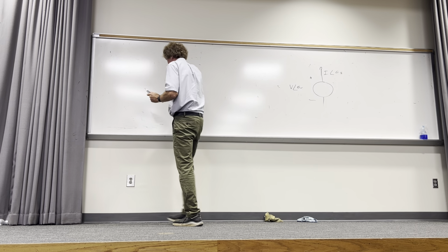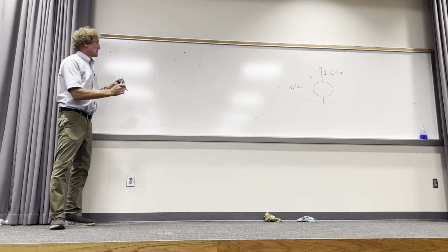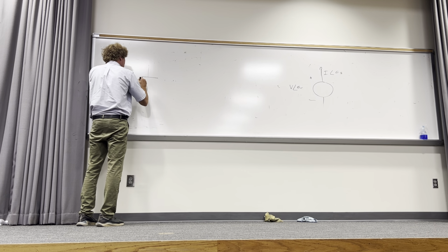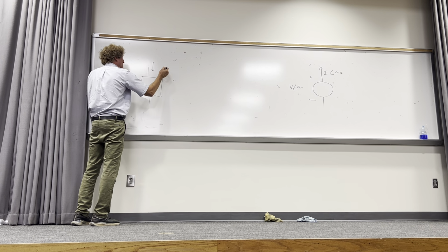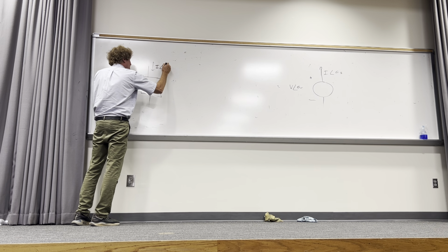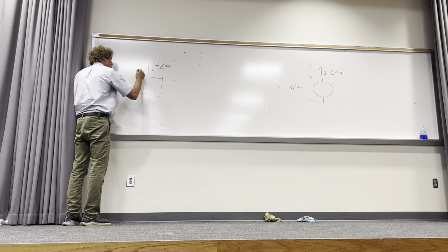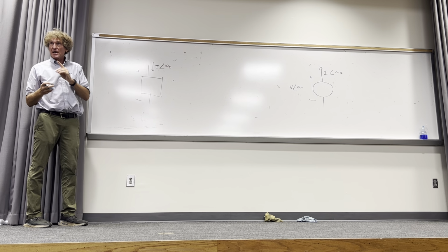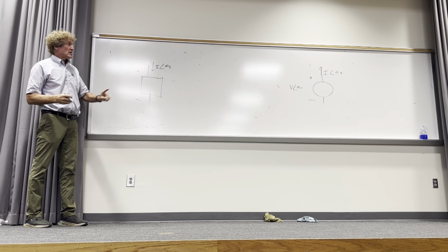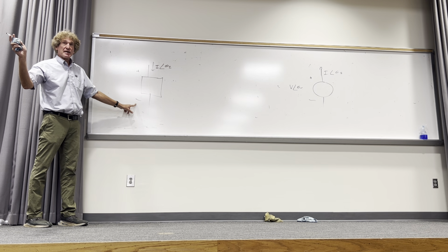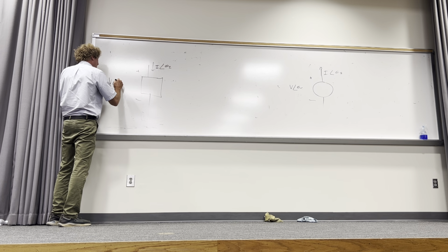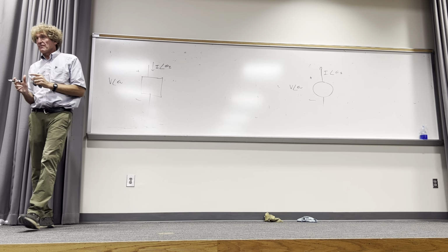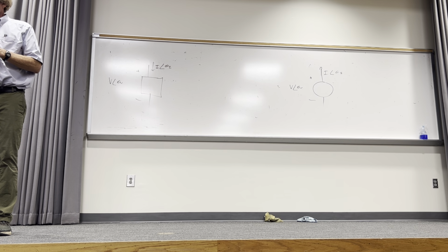And what I'm about to show you is true generally. If you have something, it really doesn't matter what it is, and this something has a current going into it, I, at an angle theta I, and it has a voltage across it. You'll notice the voltage that I'm listing is developed with a plus where the current enters and the minus where the current leaves. This is the key to getting the right answer. And this voltage is some value V at some angle theta V. Both I and V are the peak value.